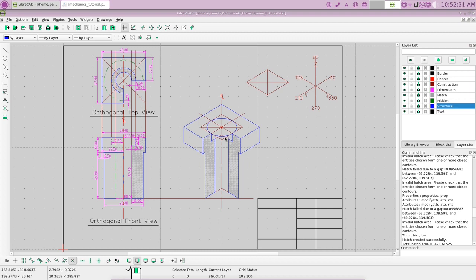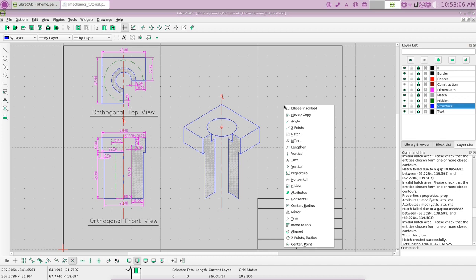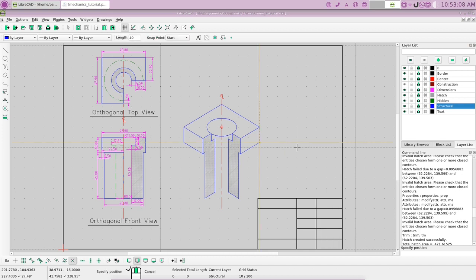Now, we need a circle down here, 7.5 lower. And in order to get that, we're going to turn off the construction layer for a minute so we can see what we have. Now let's move this point down 7.5 units so that we can put another circle in there. So let's draw a line just to get a point 7.5 units lower. Let's go with a vertical line, and let's make it a length of 7.5.